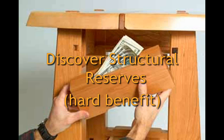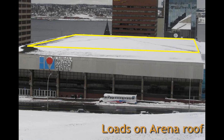For example, during the design phase you have to assume the worst possible quality of concrete and the worst possible settlements in the foundations. Once the structure is constructed, you can measure the real values of those parameters, and when you redo the calculation, you often find additional structural reserves thanks to the reduction of the uncertainty about the real properties of the structures. An example of such an application was a project we did on an arena in Halifax,